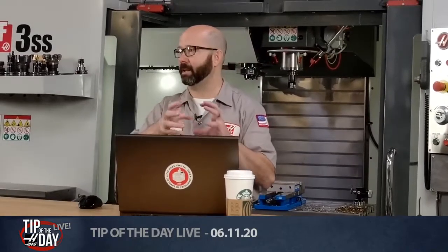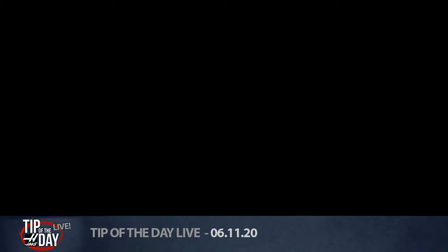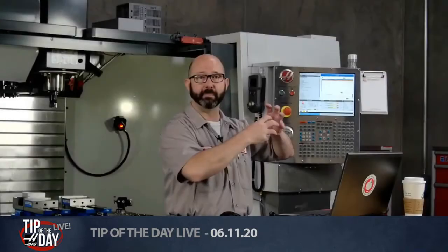The question was, if you pull out a part of your lathe and it's got a milled flat on it, can you put it back in the lathe and pick it back up? And that's the real question. Well, sure you can, but it's kind of like loading a part on a rotary on a mill. Same thing. You're never gonna get lucky enough to put that thing in if it's got a round fixture. You have to orientate it. So one of two things. You'll probably want to engage the C-axis, your M154, and then you'll want to indicate that flat until it's perpendicular to the X-axis, and then you'll take that C value and enter that as your G54 C work offset on your lathe. When you put it back in, you've got to indicate along that flat, and then set that new C-axis position as your new G54.